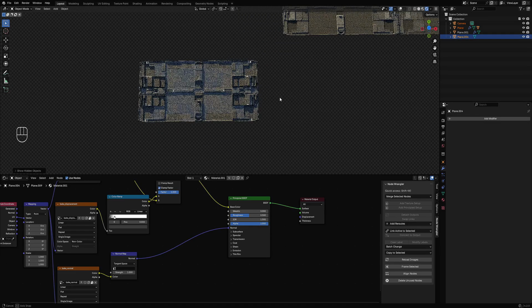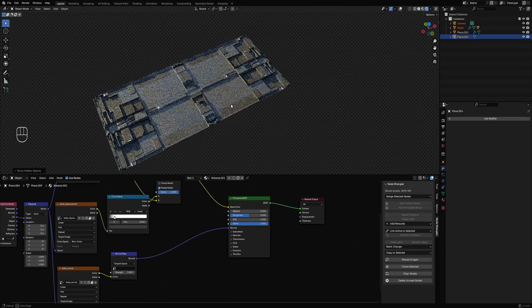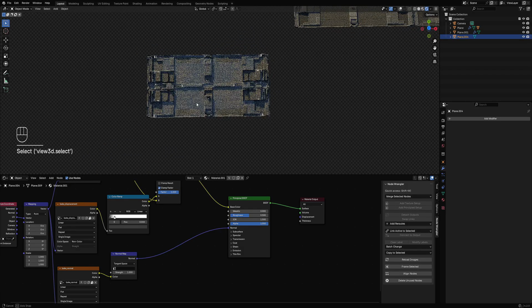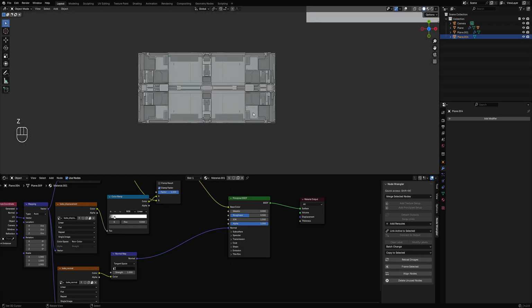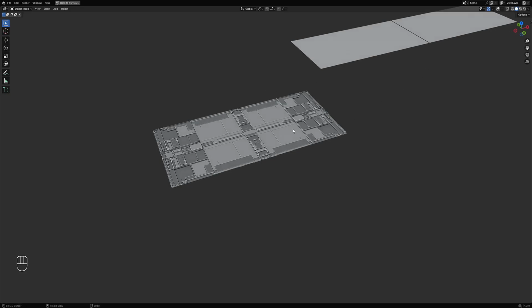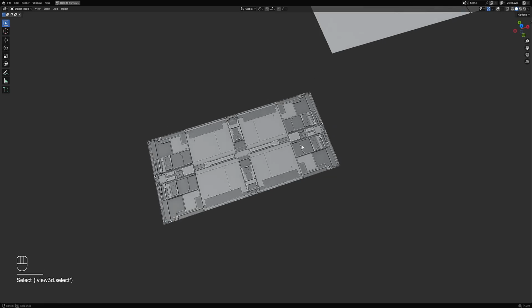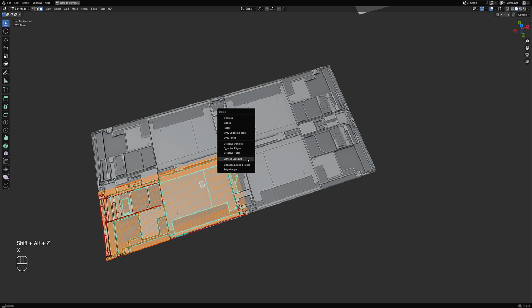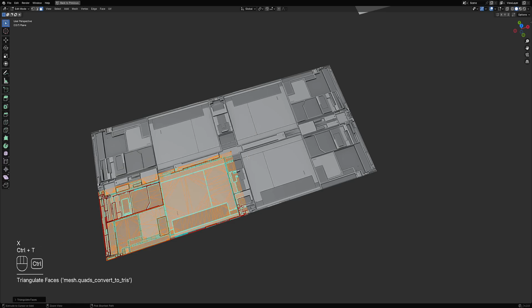So I guess this is it for now. And yeah, you can model a lot of this, and then if you want, create your own library to use for the asset browser. If you want to use just the geometry, not textures, you can just make the slider, limit the solve and triangulate, and manually fix the shading errors that you encounter.